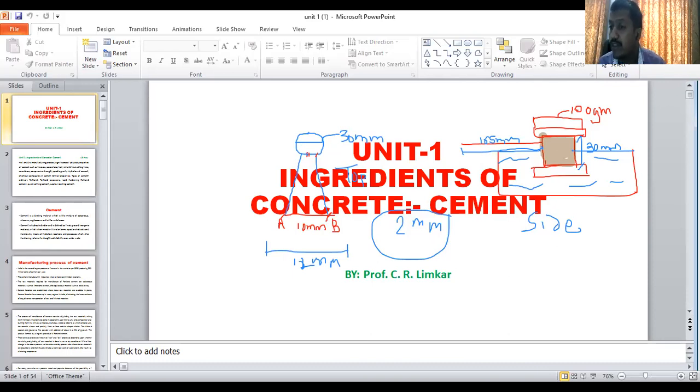Then you are going to fill that mix in this particular mold. As you can see, I have filled this mold. This mold is having a small opening at the center, at this particular position. Just see the pointer which I'm scrolling. Now what happens? You are going to keep this mold in water which is at room temperature, after filling up the cement paste in the mold.